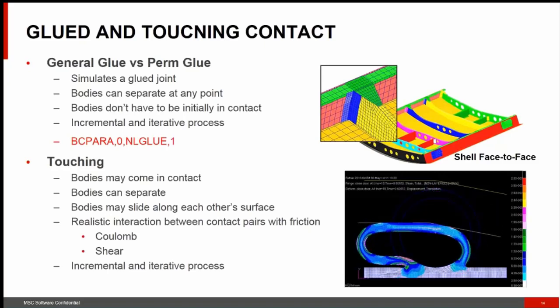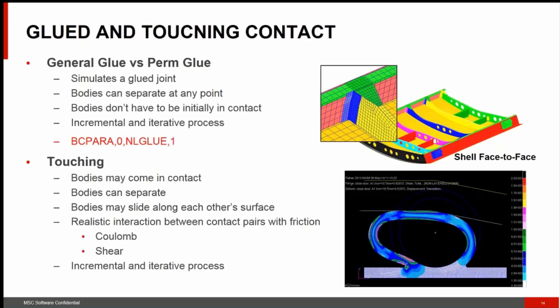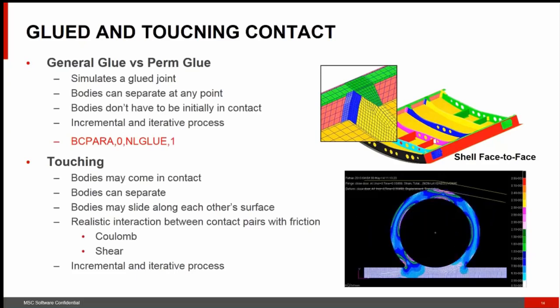It's also important to note that although we call it glue, the bodies may lose contact at any time if the separation force or stress that was defined is exceeded. So in this case, it can be separated due to unglue. Or users can define breaking glue, which is a different topic and which is not discussed here.